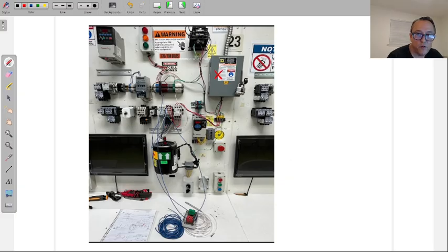If you lose one fuse out of here, the amperage of that motor immediately starts to climb because you technically lost one whole phase that the motor has been using. So voltage goes down, amperage goes up. So we have that Ohm's law principle.